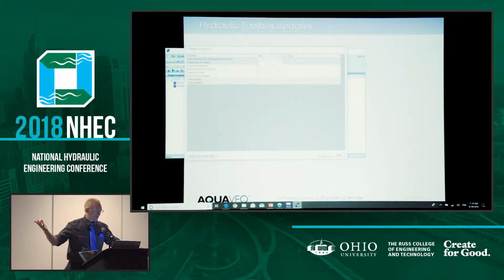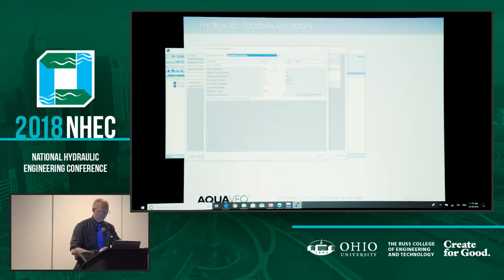So this is the new scour tool. Everything is turned off by default. If you want to see different calculations, you click to enable it. So we're going to enable long-term, and the only option here is just to define what it is that you want. This dialog is what we had previously, so it just defines the parameters for specifically long-term degradation. We've added this spot where you can just specify a scour depth. You know that your scour depth in the long term is going to be 6 inches, so you just want to be able to enter that in directly.